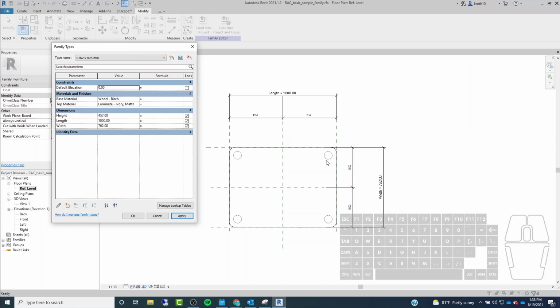You can see these feet here for the table, and those are actually moving with it. All right, so that would be an example of a constraint where they have set up some sort of a lock to tie the feet position to the edge of the table, so that if anything is adjusted, it will move, and the feet wouldn't just stay where they are by default.